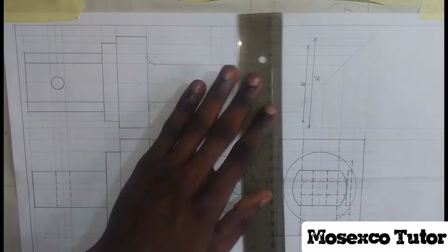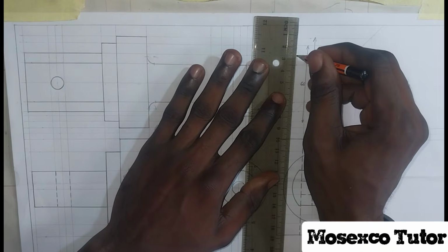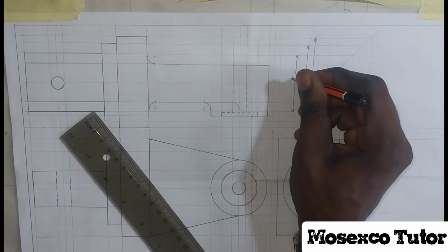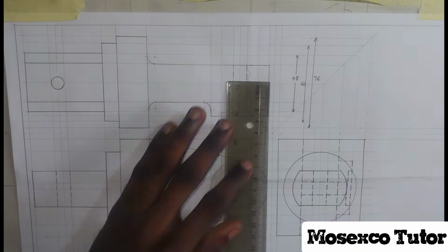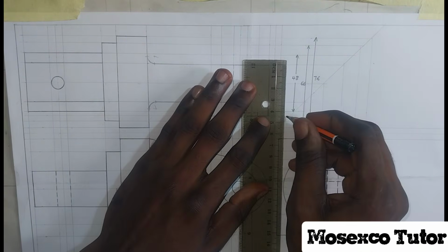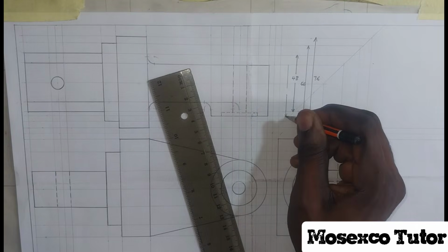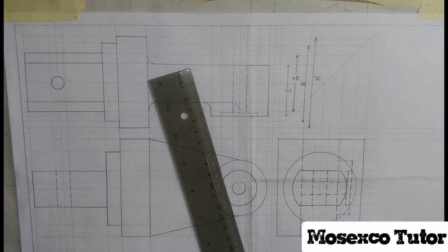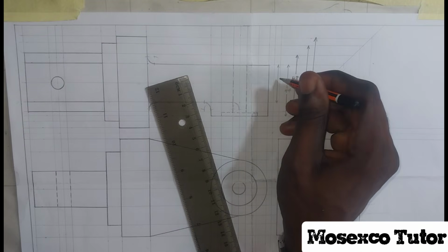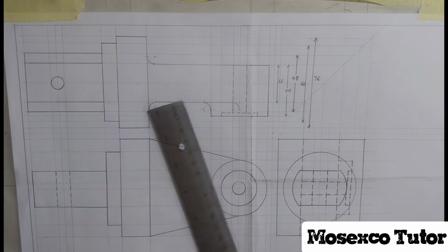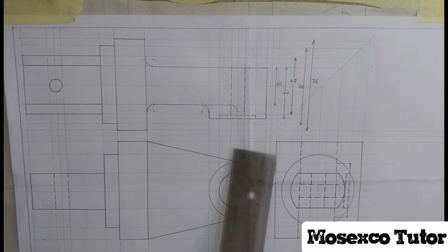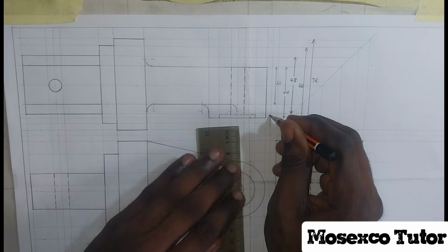Now a quick explanation. In this diagram, we are given a spigot and we're asked to draw it in third angle projection. In third angle means the plan will be up while the front and the end view will be downwards. But now we are asked from the question that the side view be to the right hand side of the front. The side view is to be to the right hand side of the front. That's why we place it here.